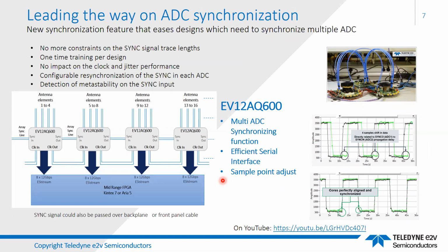So that's already an interesting feature. There's no need for multiple FPGAs for 16 elements. And there's also no need to double the number of ADCs that you require. For example, a two-channel ADC would need double the number of ADCs, so that doubles your board area and doubles your cost as well.